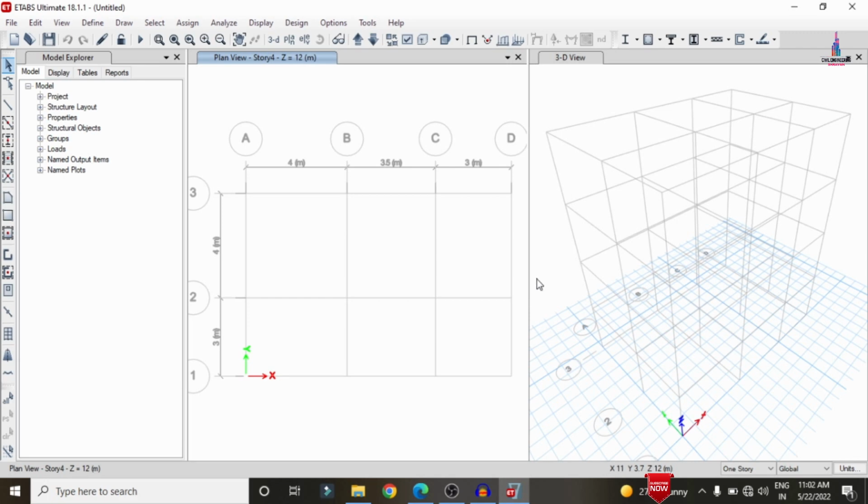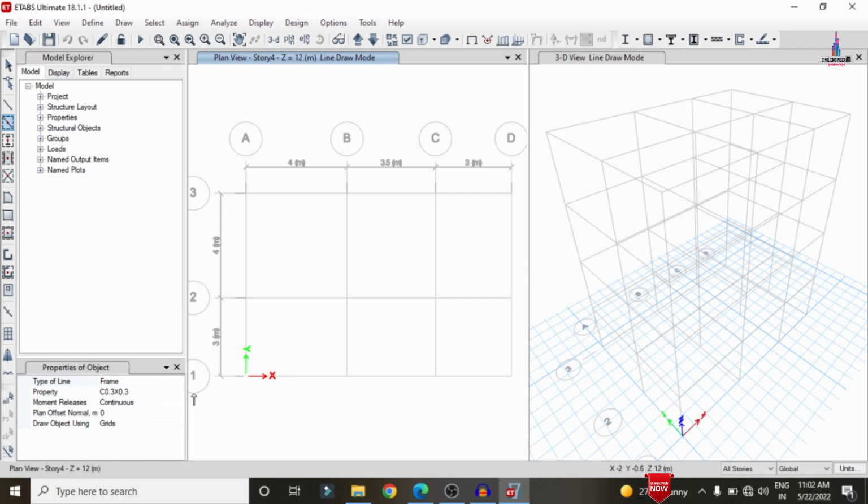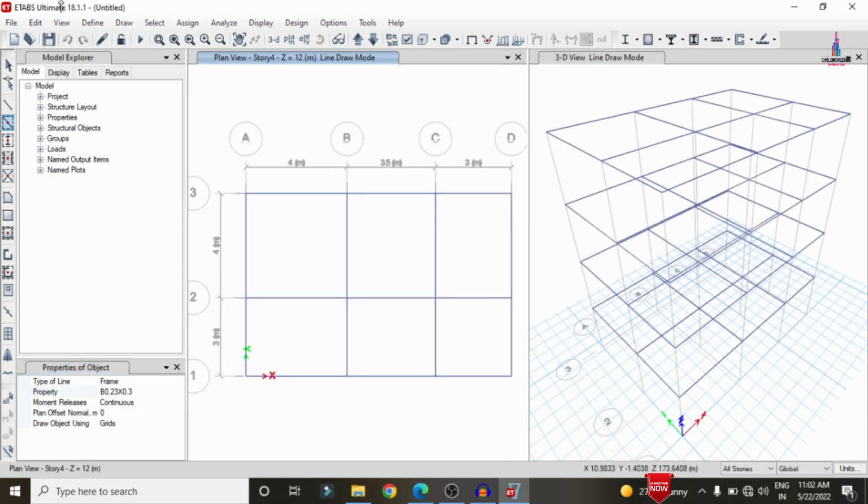So for that, firstly I will select the one story option to the all stories option. Okay, then after that we have to select the beams assignment option. Basically we will assign the beams regularly by using this quick draw beams option. So select this property and select the property name here as beam. You can drag to the respective model here like this, so that it will assign the beam property here.